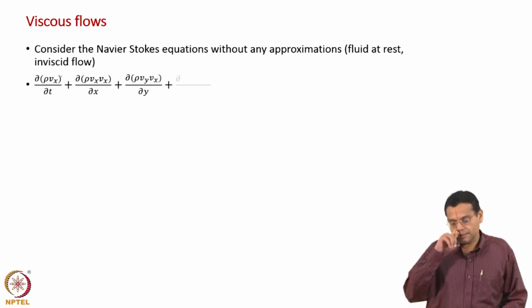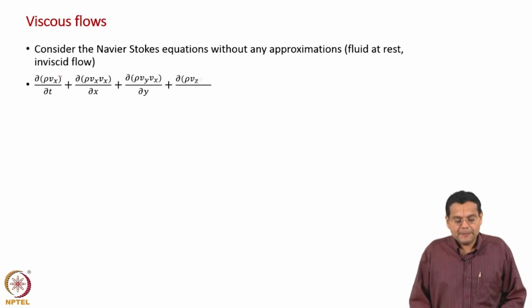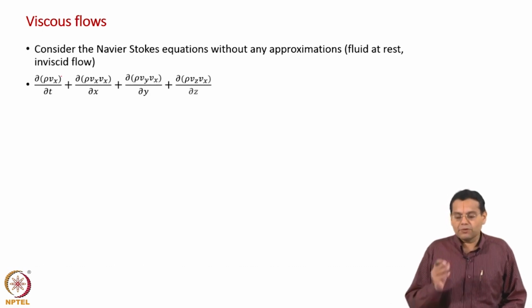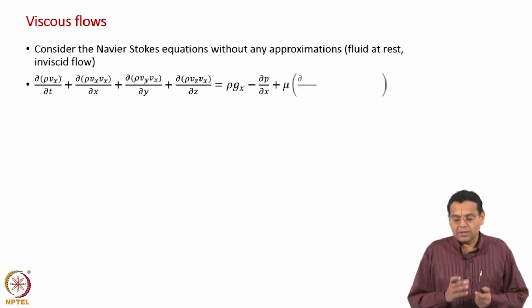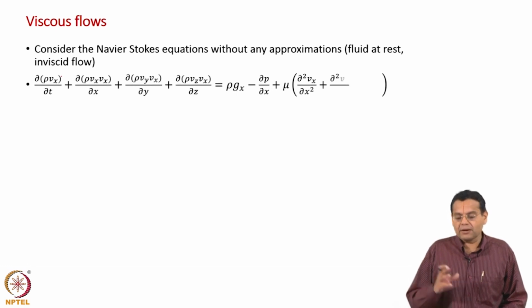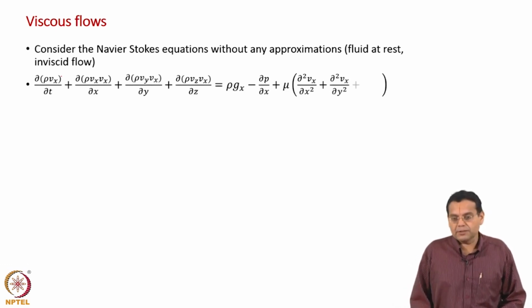First we said the velocity is 0, fluids at rest, then we said the entire fluid body has one velocity, all the points have the same velocity. So, we can represent it as one acceleration term on the left hand side, then we neglected all the viscous terms on the right hand side. Okay. So, now we are considering all the terms.